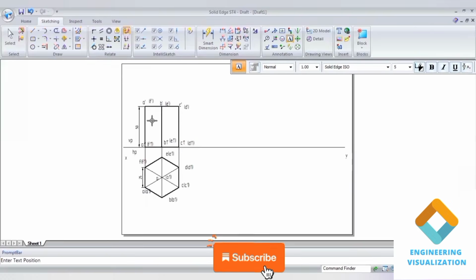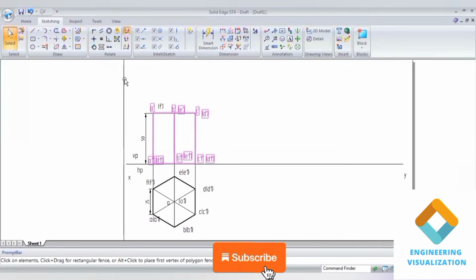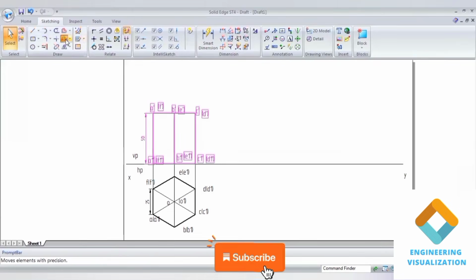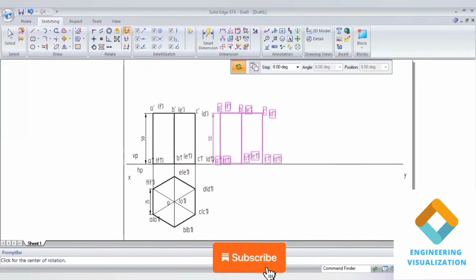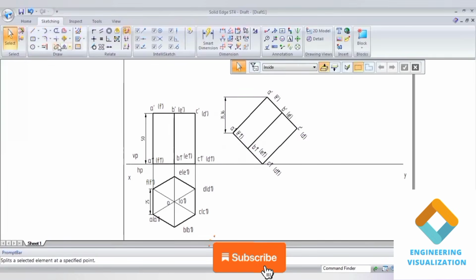Now we need to copy the same diagram using the move command, and we need to incline it with the base edge. Inclination to the base edge is given. Actually they give the angle of inclination to the axis, but we incline with the base edge, which makes it easy. So use the move command, create a copy, slide along the XY line, then go to rotate and take the base edge. The inclination is 45 degrees. So incline it 45, and it has been inclined.